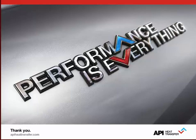All right, and last question here we're going to squeak in. How is pitch geometry decided, 90 versus 60 degree? Sure. That's relative to the tube pitch. And the main reason there is obviously the fluid dynamics on the shell side of the heat exchanger.